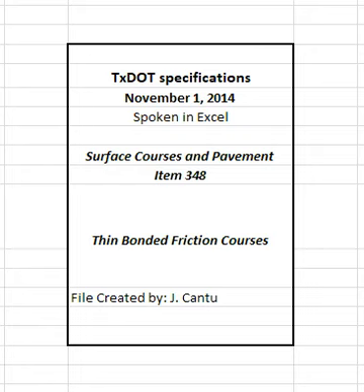4.7.3 Laydown operations. 4.7.3.1 Thermal profile. Use a handheld thermal camera or a thermal imaging system to obtain a continuous thermal profile in accordance with Tex 244F. Thermal profiles are not applicable in areas described in Section 348.4.9.5, miscellaneous areas. 4.7.3.1.1 Thermal segregation. 4.7.3.1.1.1 Moderate.